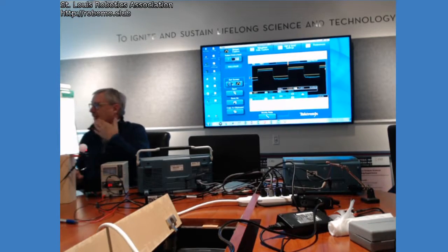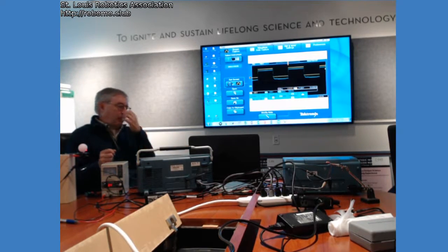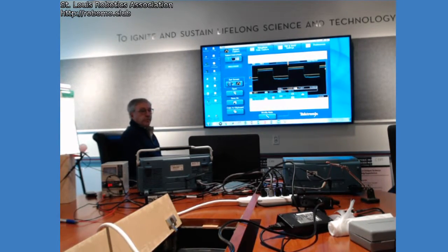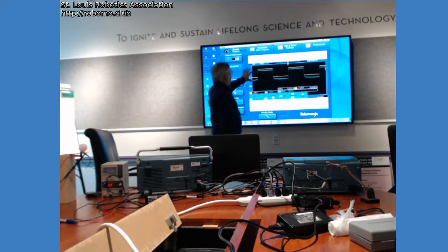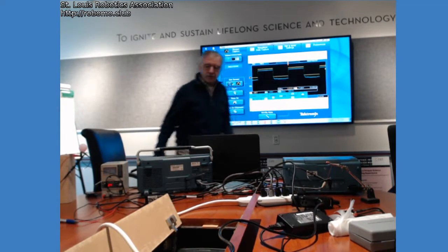So you're also saying distance? We have some of those resistors in those kits. Would that help? No, I don't want to start, because we'll all be watching me try this. Is the signal not readable? If I hook this up to an Arduino, is it not going to figure out the frequency? Can you definitely figure out the frequency? Well, it's the square shape, right? And this is 2 volts. So you've got an A to D converter on your Arduino, and it's plenty fast to pick up this 60 hertz.